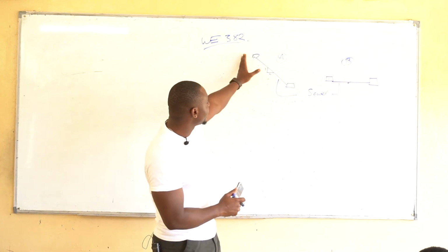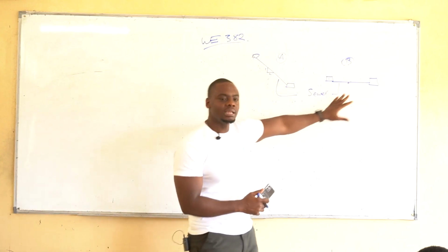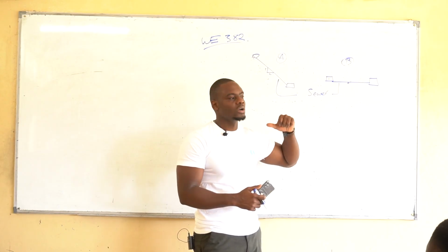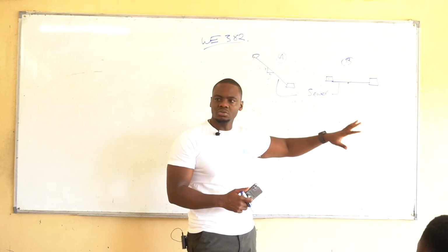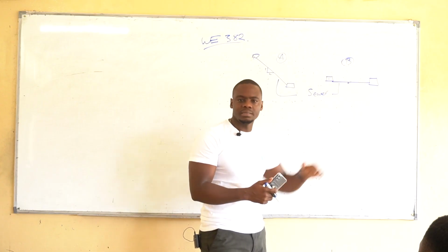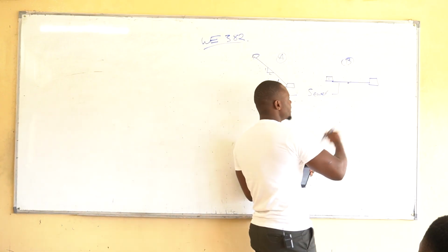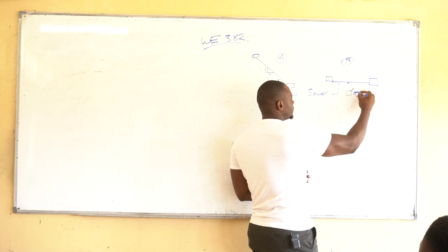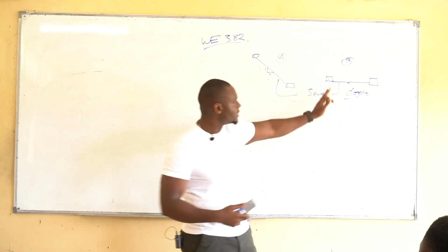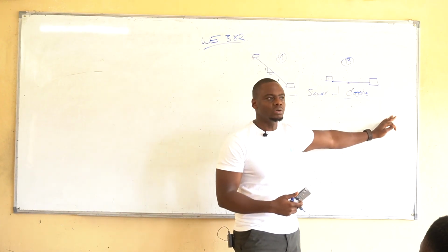So the difference between laying a sewer pipe in that format and that format, without considering calculations or the characteristics of your waste, is that this one is too less steep, so you are likely to experience clogging. Because remember, you don't have a pump pushing the fecal waste. You're relying on gravity.